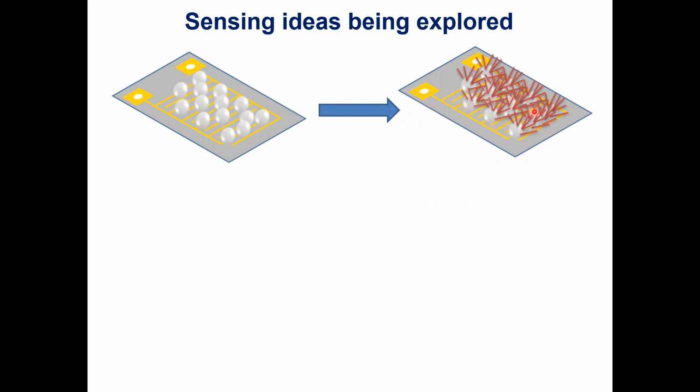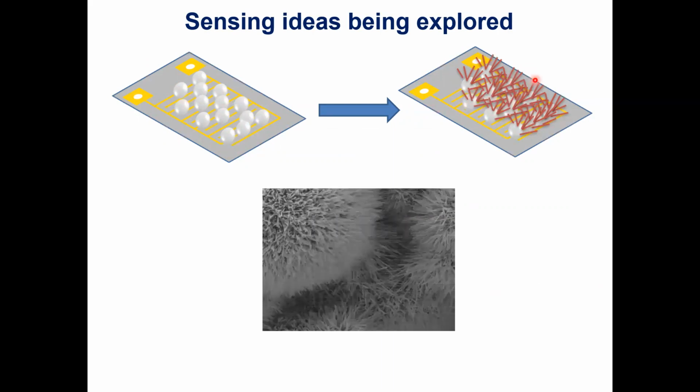Now this becomes your sensor, where you can do gas interaction on the TiO2 fiber, and the signal would pass from the titanium alloy particle through the TiO2 fiber, where the gas is interacting with the neighboring particle, and the signal would be carried. And you can create fiber-fiber contact by strategically positioning these titanium alloy particles on the sensing platform.